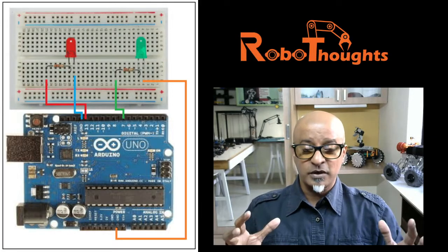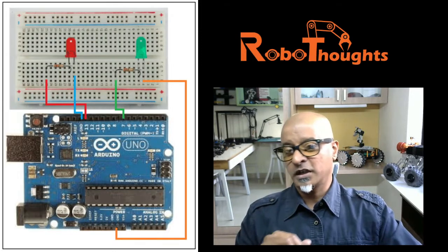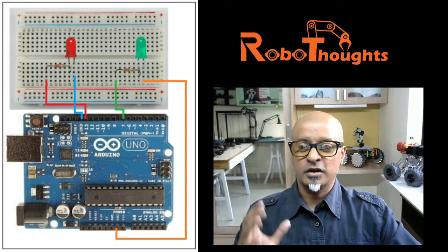In Arduino UNO, there are two or three ground pins which you may use. But as we expand further, we may need multiple ground pins. So the best practice is to use the common railing in the breadboard as one single ground, connected to one single ground pin, so that you can distribute your current evenly. Let me show you how I did it.